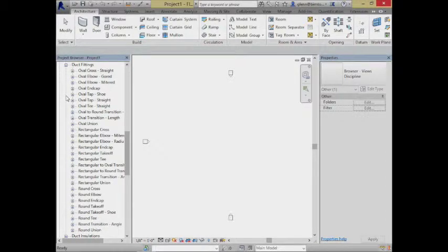And you like to have those available because here's the way Revit sort of works. We're going to go through and say we got a fixture over here. We want to take the line to over here. Please help us figure out the piping and all the connections between those things as much as possible. And if it has a fitting, if it has a size available in its library of parts, it knows what to do. If it doesn't have a size that would fit the condition you're trying to do, it'll stop and say, whoa, I don't know what to do. I can't auto-route that for you.